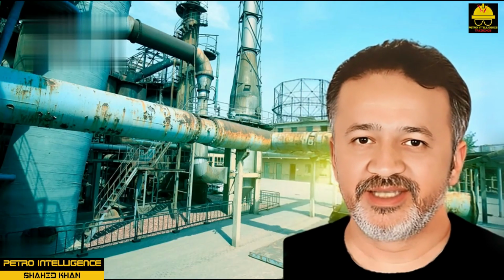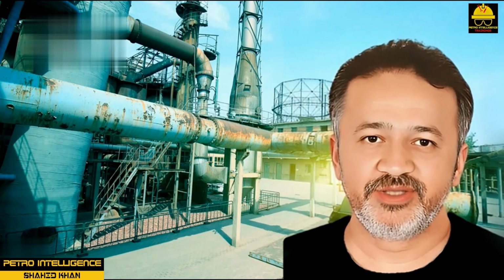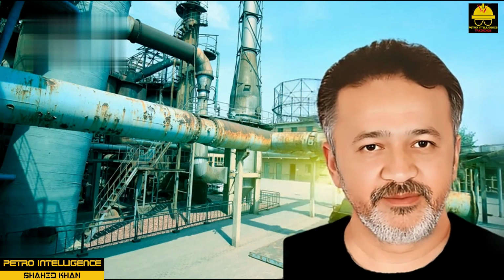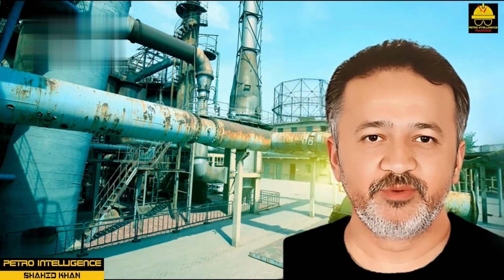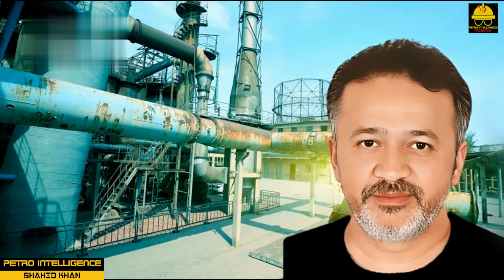The SHP steam is generated by a boiler and is supplied to the SHP steam header. The typical pressure of the SHP steam is 1000 to 1200 psig. SHP steam is supplied to turbines, which drive compressors. In order to control the pressure in the high-pressure steam header and to transfer excess amount of high-pressure steam to the high-pressure steam header, a letdown, pressure-reducing, station is provided between the SHP steam header and HP steam header.